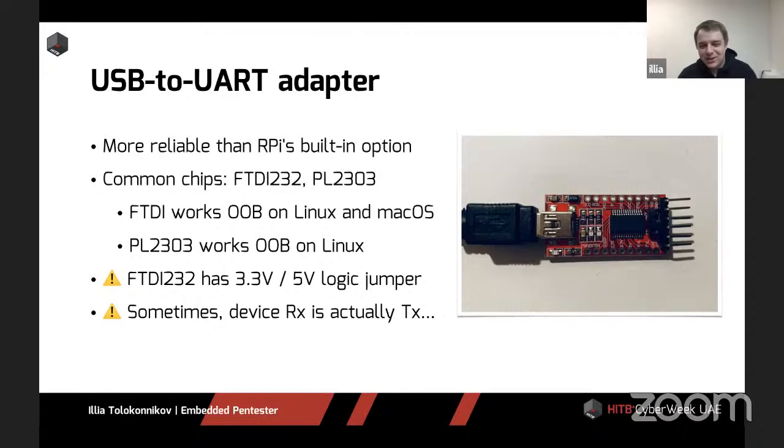And sometimes, don't believe everything that's written on the device. We received one batch of devices with wires sorted to every pin we needed to connect to. We connected them as usual per labels. And then after half a day of pulling our hair out, we discovered that the wires for RX and TX were mislabeled and just wasted half a day. So right after that, we quickly test those things by switching wires to see if things work. And these small things sometimes can even be soul crushing, but I guess when you're in this business, you need to account for those things too.